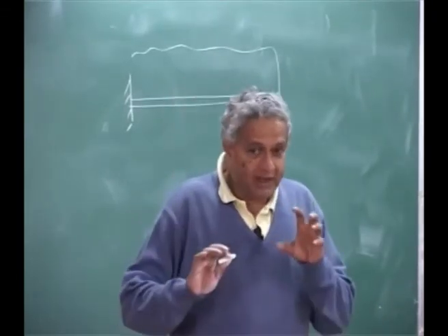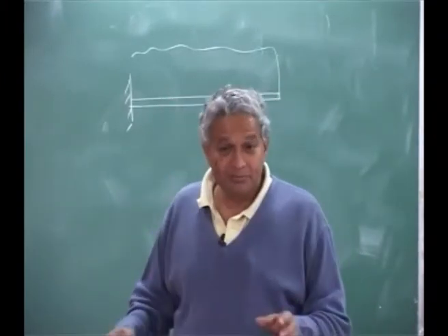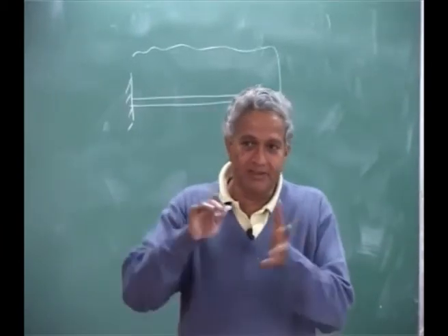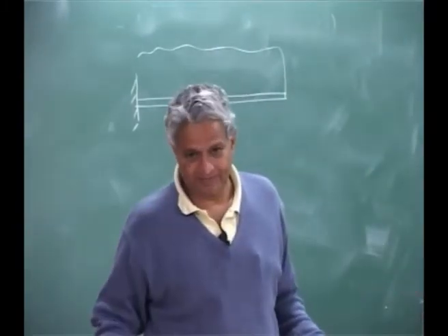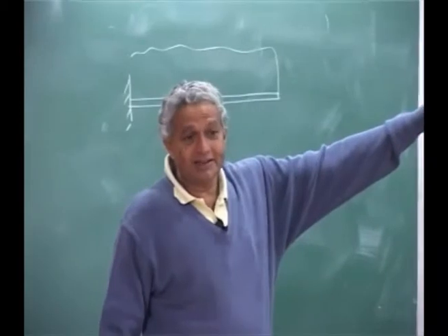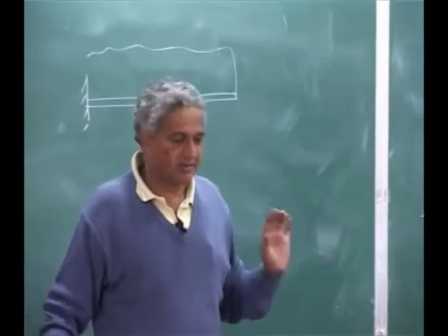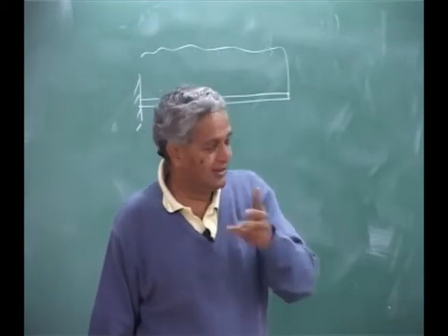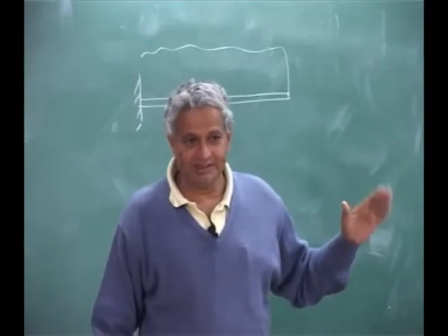So you see why, when we want to say is it self-adjoint or non-self-adjoint, this becomes too mathematical, it is because of the solution technique. And you say that, hey, if the operators are of this type of form, then they have this kind of a solution. Now you have seen we have reduced the infinite degree of freedom system to a finite degree of freedom system. Static aeroelastic problems will be algebraic equations, whereas dynamic aeroelastic problems will be ordinary differential equations in the finite domain.